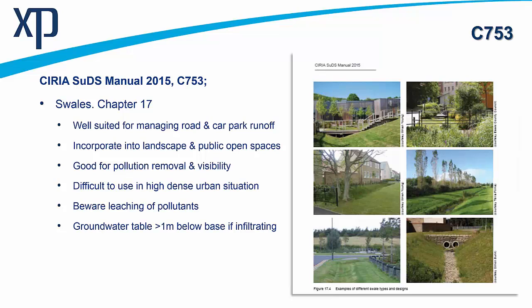They will be difficult to use in high, dense urban situations. They are a bit of a challenge if you have a steep sided slope, a topographical site with steep gradient across it. And we do need to be careful of infiltrating if we are taking diffuse pollution from, say, car parking areas, that we don't leach that contamination, if you like, down into the aquifer down below. So to that extent, we need to be mindful.